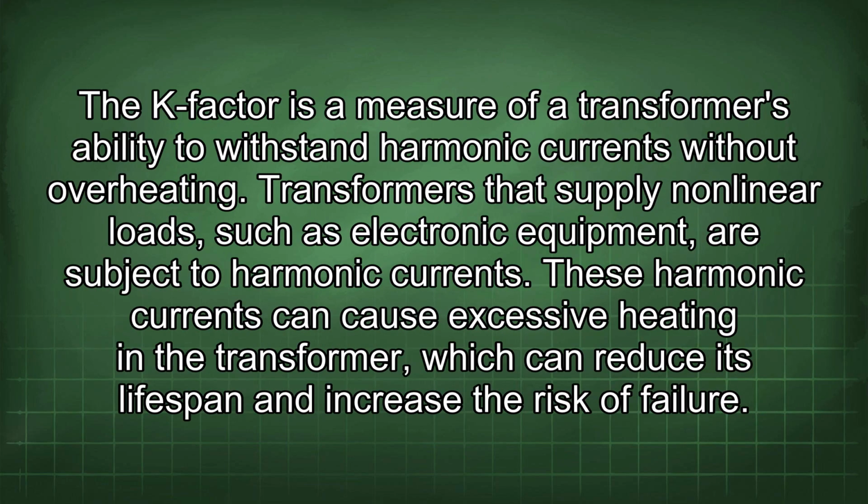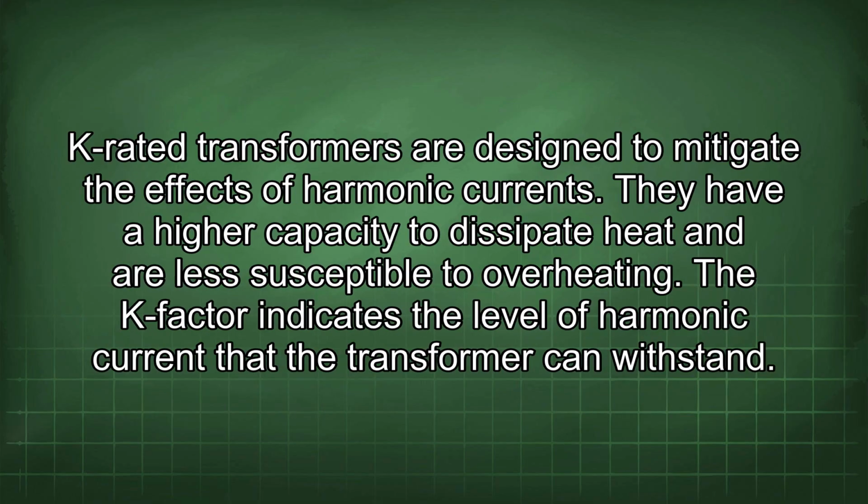The K-factor is a measure of a transformer's ability to withstand harmonic currents without overheating. Transformers that supply nonlinear loads, such as electronic equipment, are subject to harmonic currents. These harmonic currents can cause excessive heating in the transformer, which can reduce its lifespan and increase the risk of failure. K-rated transformers are designed to mitigate the effects of harmonic currents.